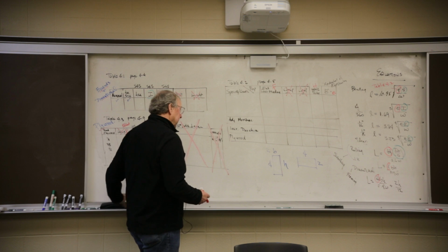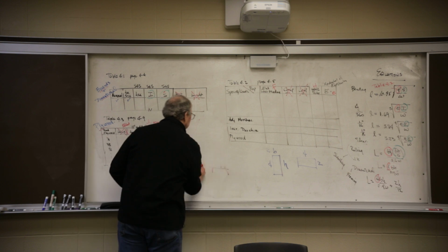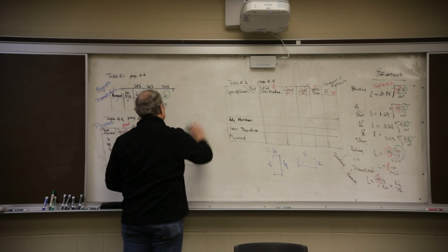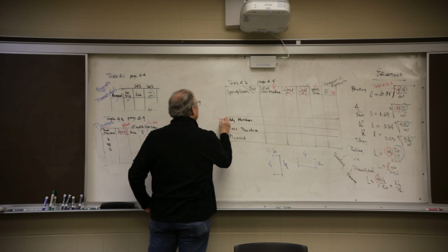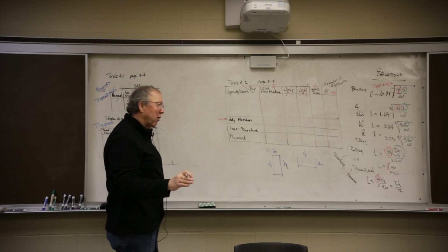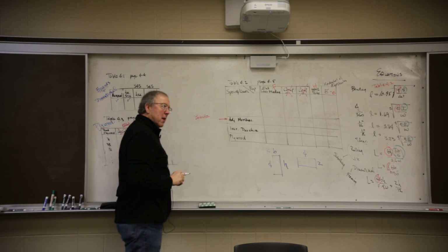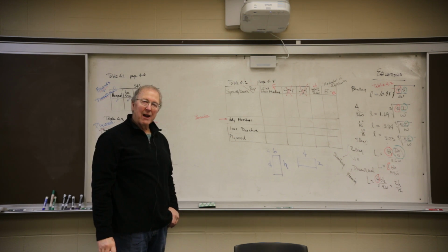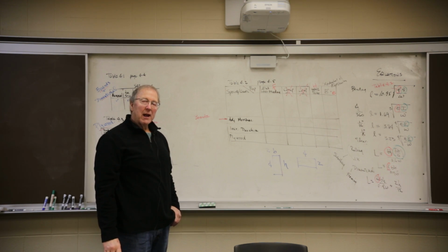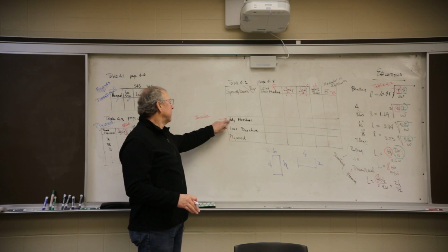Okay, I'm gonna give myself a little more room here. I'm gonna erase part of this since we've already talked about it. Okay, this will be used for, in your case, for boards. Why boards? How's it going to get wet? It's going to get wet if you pour concrete and the concrete lays on it and the material sucks up the moisture in the concrete. That means it's sheathing. So this has to be for sheathing.